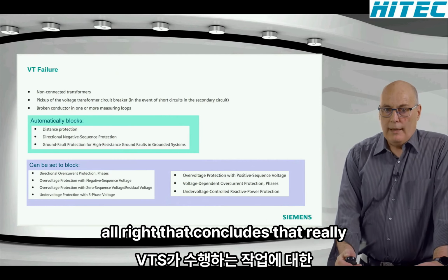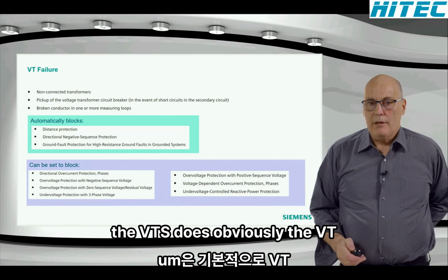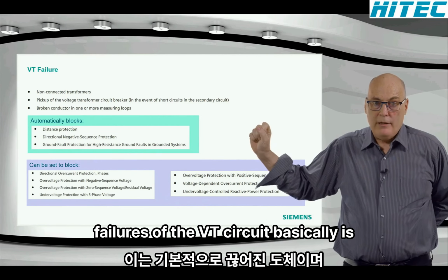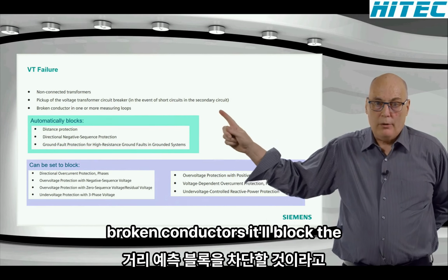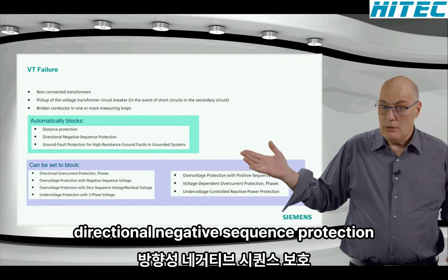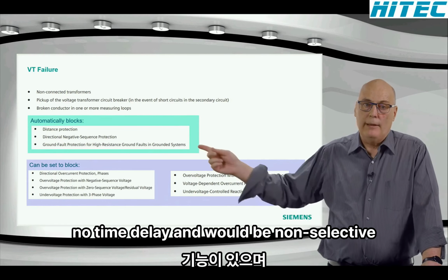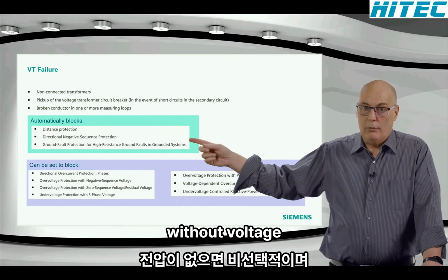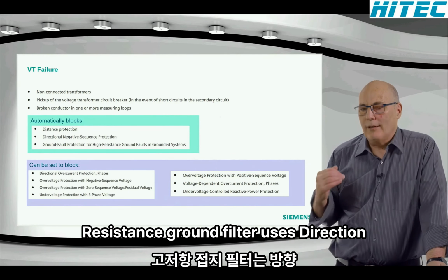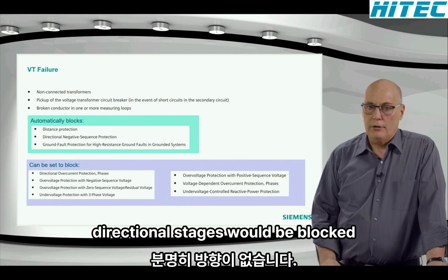All right. That concludes this, really just with the final information of what the VT does. Obviously, the VT will detect failures of the VT circuit, basically broken conductors. It will block the distance protection, block the directional negative sequence protection. Those are protection functions which could operate without or with very short time delay and would be non-selective without voltage. And also the high resistance ground fault protection uses direction measurement. If the VT fails, it obviously has no direction, so those directional stages would be blocked.